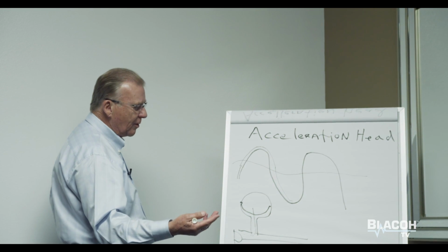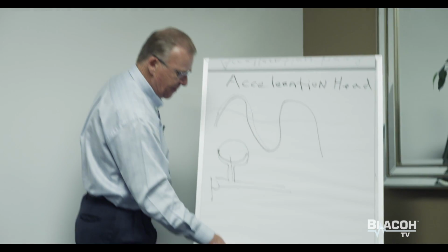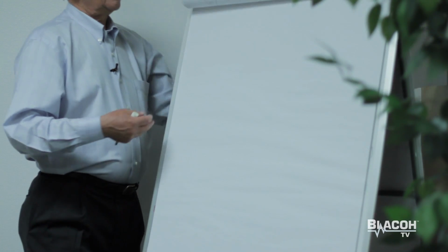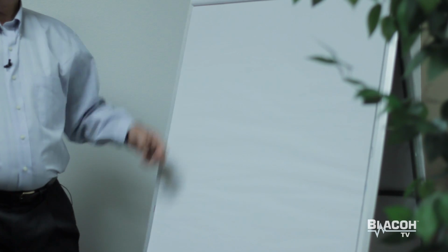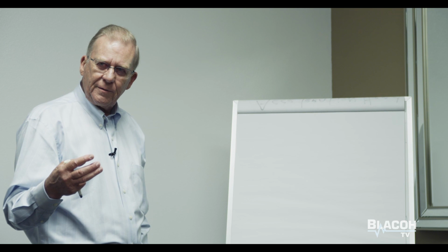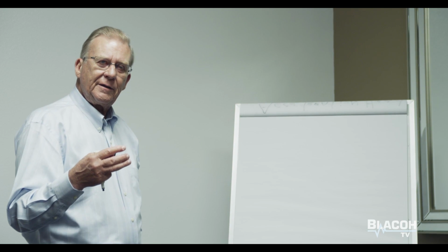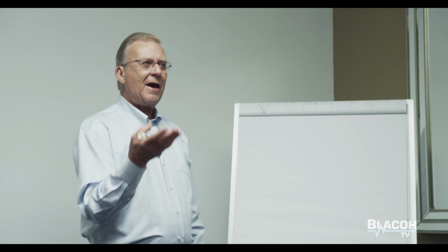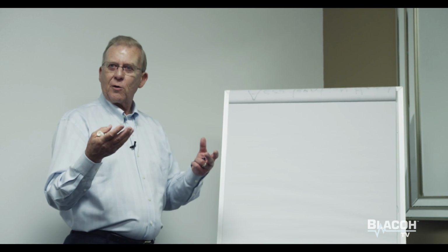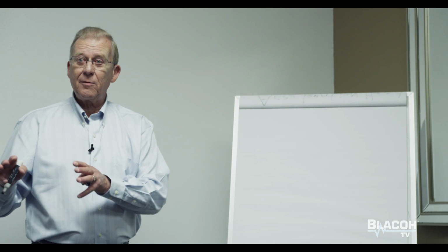Where we can have problems is on the inlet side of the pump. Because now that acceleration head can work against you, and you only have atmospheric pressure as the form of energy or power on the inlet side of the pump.